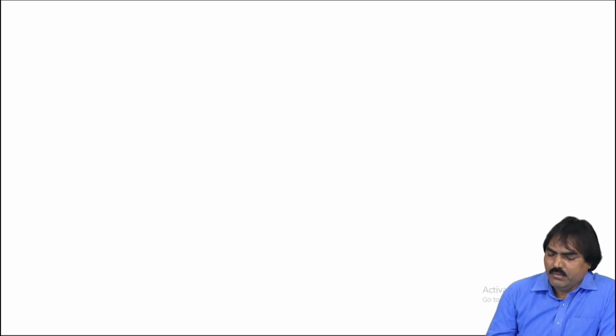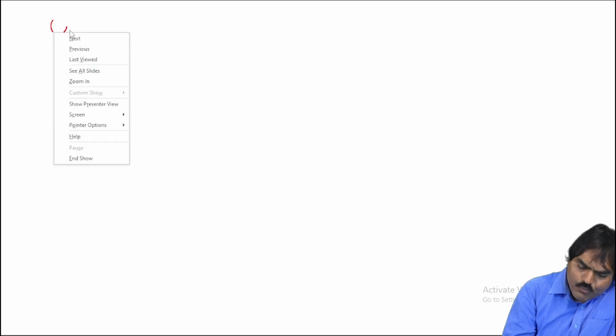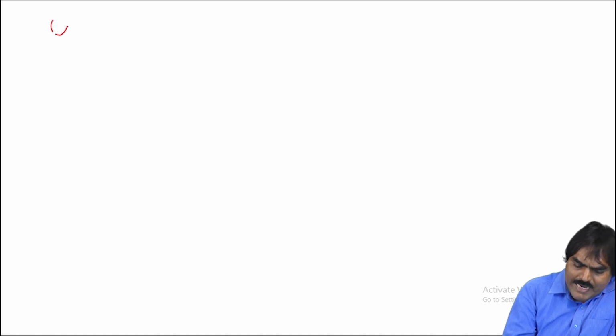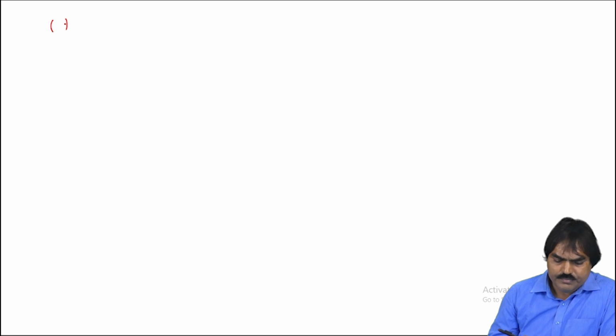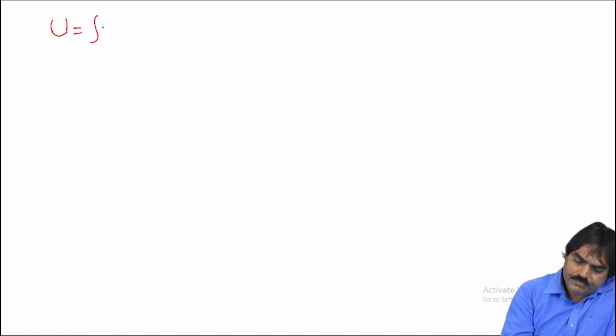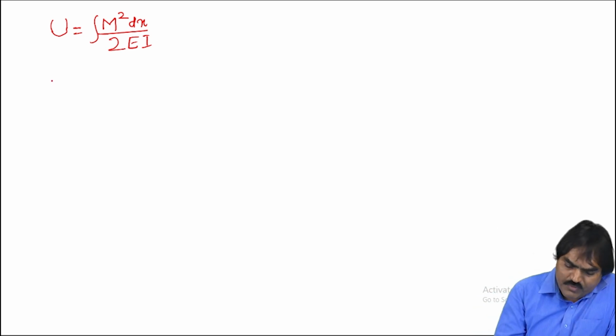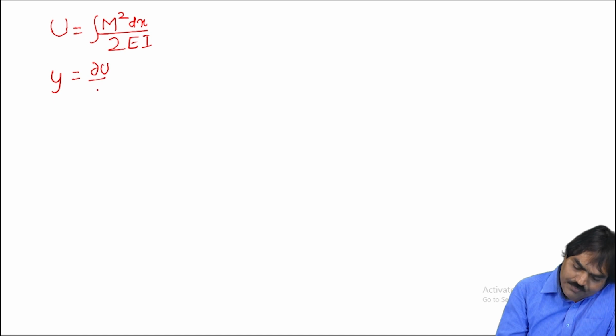Okay. Now, see, the energy is given by integral of M square dx by 2 EI. Then what is the deflection? Y is equal to dou U by dou P.